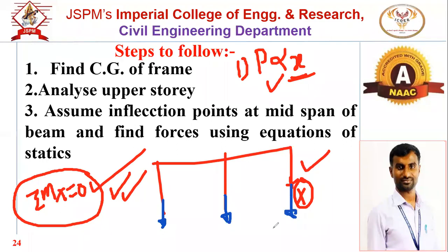So these are the axial force. Now in case of portal method, we are using the summation fx equal to 0 condition to get the h. So this h we have got using the summation fx equal to 0 in the portal method. So horizontal shear is twice for interior column as that of the exterior. But here we have to use the third assumption, and we have to make the summation of moment at mid height for the right end column to find out the vertical forces, or we can say axial forces.